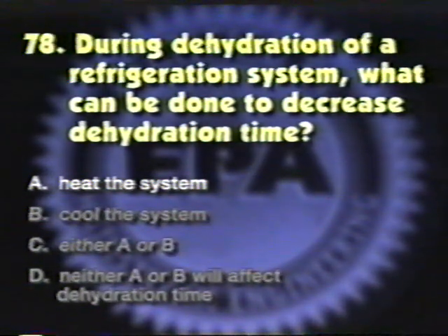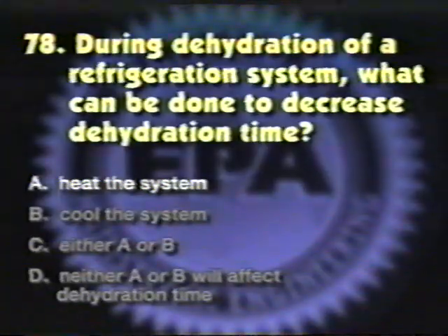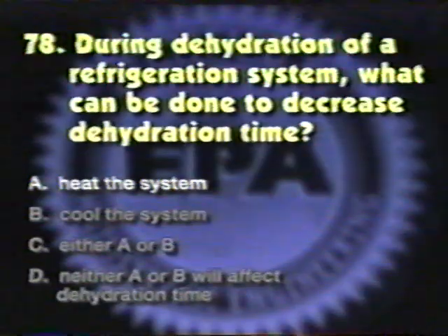During dehydration of a refrigeration system, the refrigeration system can be heated to decrease dehydration time. So the answer is A. Heat the system.